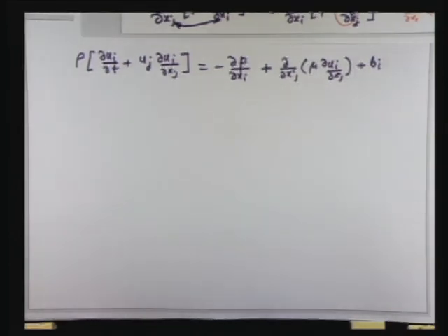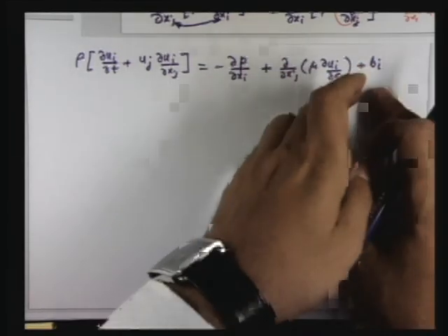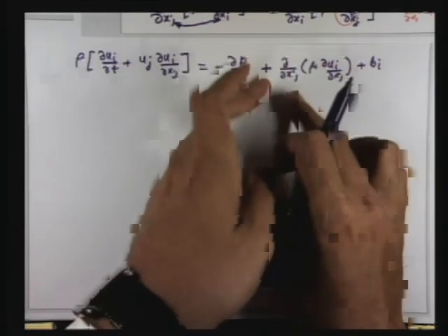This is not the general Navier-Stokes equation because we have considered the special case of incompressible flow, which is in the purview of the problems that we will be solving for the tutorials that we will organize after this. If it is a compressible flow, there will be an additional term with lambda, just as there is a term with mu.